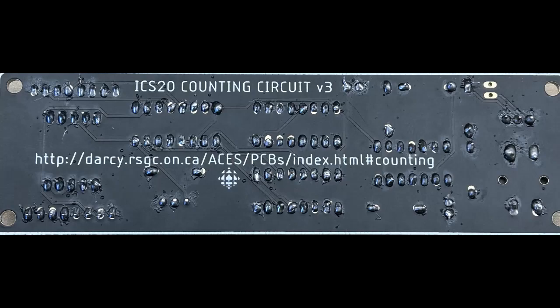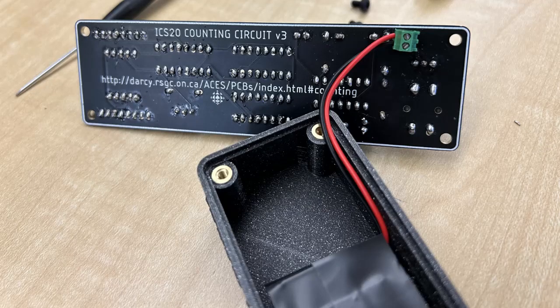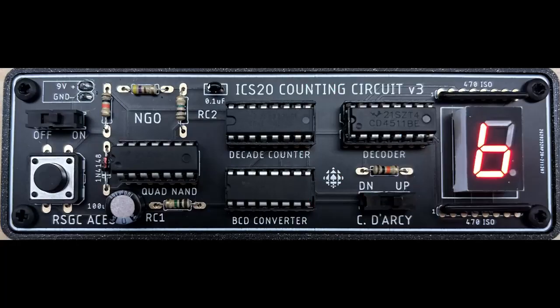Next, the counting circuit PCB. This transfers the breadboard prototype to a permanent PCB setup. This PCB requires the soldering of many materials already in the circuit. It adds a 100 microfarad electrolytic capacitor, 2 resistor networks, a terminal block, and a 0.1 microfarad capacitor.